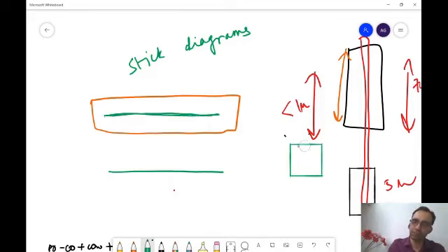Can I do that? Okay, so you're not representing the length of the channel. I'm just representing the width of the active region. I'm not even talking about poly yet. The channel hasn't come up yet, only active has come up. I'm not using rectangles, I'm just using sticks. Okay. That is why it is called a stick diagram.